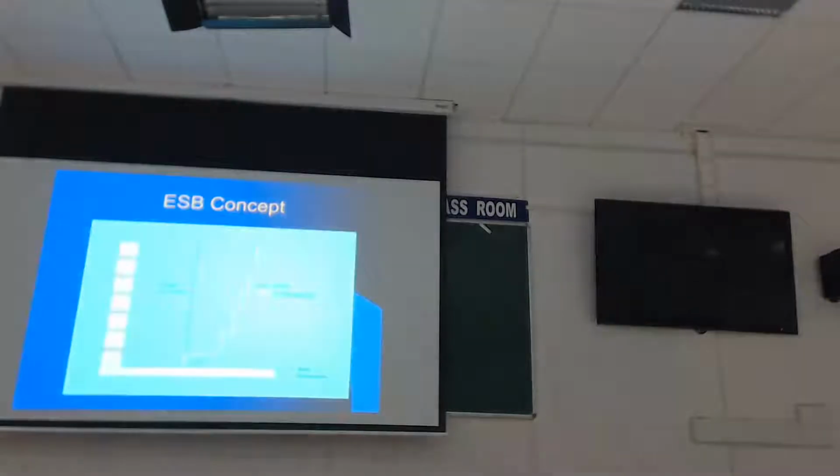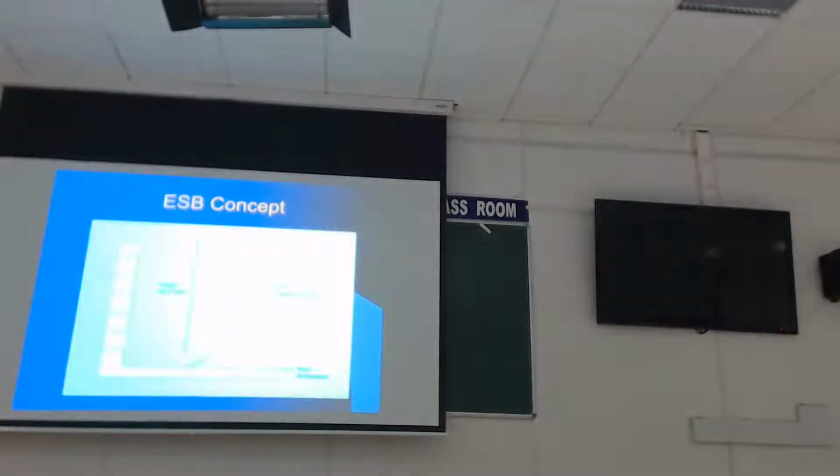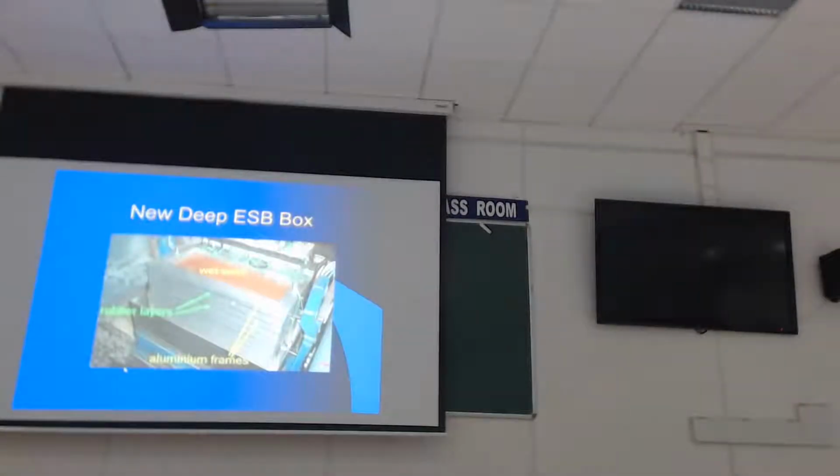Once we have done this little box, this box at say 50G can simulate something like 15 meters or 18 meters of soil. So we weren't happy with that. We built a bigger one, which can simulate up to 40 meters of liquefiable soil.